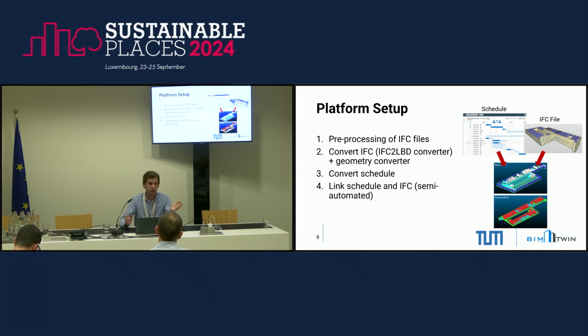So if there are some HVAC systems that are not relevant for the use cases, we remove them to make sure that they do not blow up the graph without need. Then we have to do the conversion process, from IFC to RDF using existing converters. And we've added some extensions to also include geometric information, to make sure that we can use it, for example, for scan-to-BIM approaches.